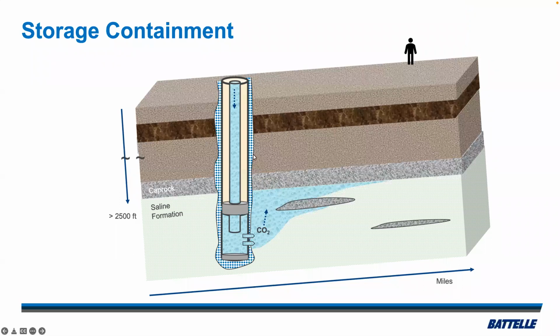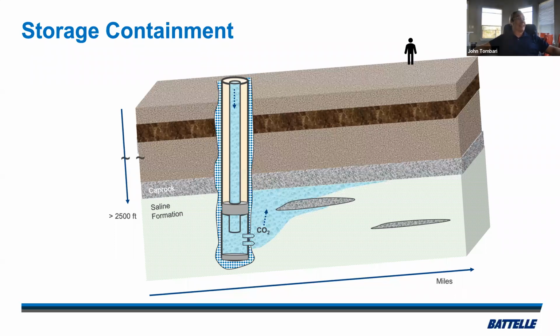Okay. Yes. The cement, in the blue and white, squeezes up through the backside of that casing, hardens, and now you have integrity and no fluids can move behind that casing from zone to zone. And a wireline or other tool service is used then to lower explosive charges into the well, blow a hole through the casing, through the cement into your saline formation so that now you can put tubing or a thinner casing string down the middle through which you inject your liquid CO2, and it goes through the casing, through the cement, into the saline formation that we spoke of.